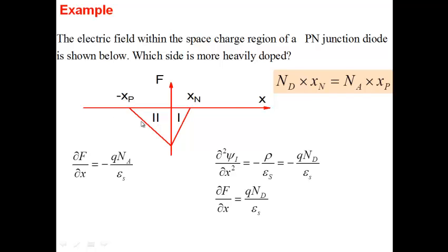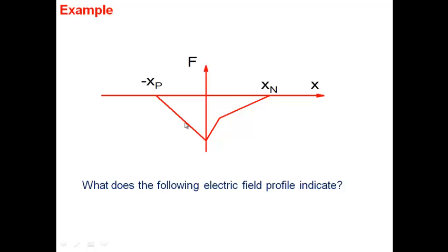Which means uniform doping here. Now here, is this uniform doping? Yes. And then this is also uniform doping. That's also true. The slope here is higher, meaning higher doping. And then the slope is lower, which means lower doping. So close to the junction, I have some higher doping, and then I have some lower doping here. Okay. And if I give you the numbers here, you can figure out how much is the doping here and how much is the doping there, right? So you can go back and forth here.